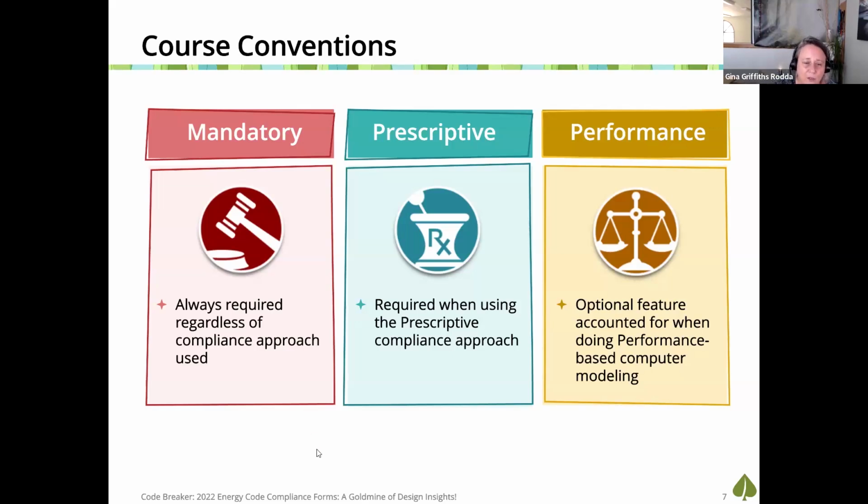So mandatory requirements apply across all scopes of work, whether it's new construction, the least expensive time to integrate energy efficiency, or additions and alterations in which now we have existing infrastructure. And when we look at the cost effectiveness analysis of the code, the rules most often change, but not when it's mandatory. Prescriptive is where things will change based on building type, based on scope of work, new construction, additions, alterations, and will change based on the climate zones.